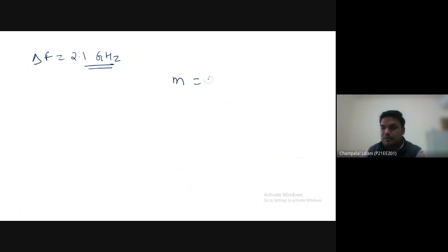So, M equal to 2nL by lambda. Ideally you should get M as 1, meaning only a single mode. So if you put M equal to 1, then 2nL by lambda equals 1, and this L will be lambda by 2n.